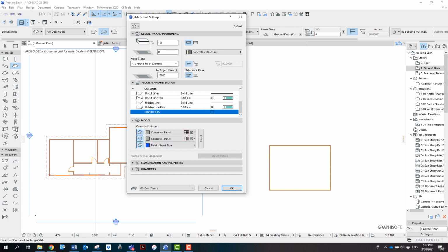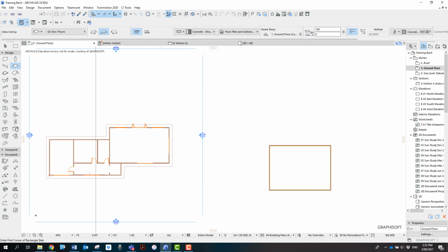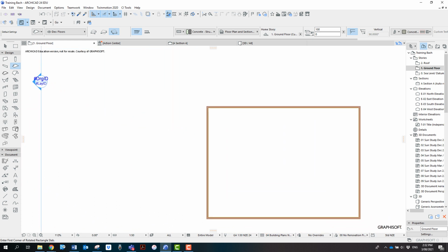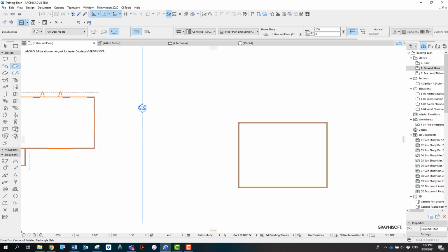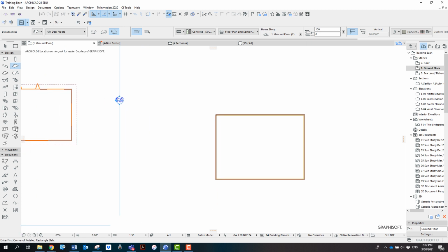And you can override the surfaces if you like. And basically, I'll just draw one. I'll just use this geometry. And what I can do is just set up a vector along here and here. And then Archicad will extrude it down. And you can then just click in the corner and we should have a slab. And that's basically the slab settings.